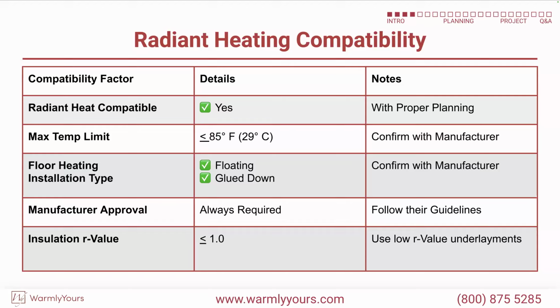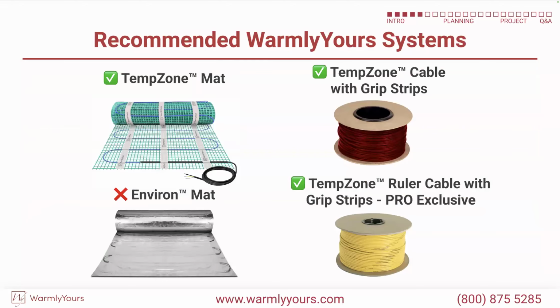So if that's the case, you don't want a programmable thermostat because you can't program in different temperatures at different times. You always have to keep it the same. So if you want it at 85, buy a manual thermostat, and we'll show you the thermostats here in a little while. That's the one you're going to want because you can't do setbacks. So always check, can I do a setback, and what's the max temperature that I can do? Good information.